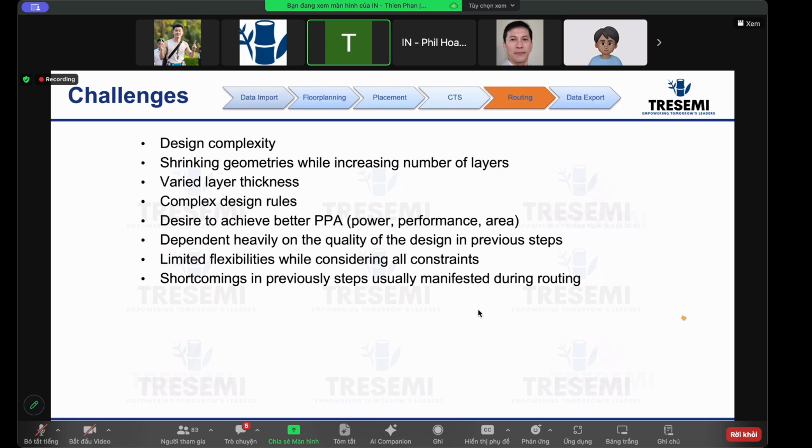So it does know the wire length, the layer and everything, and then it can calculate precisely what the delay or the RC is, even though it's an estimate. It can be very, very precise actually. So the answer is yes, it is a prediction, but it can be very accurate.